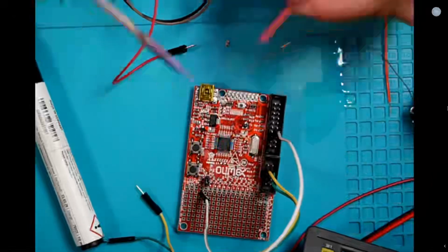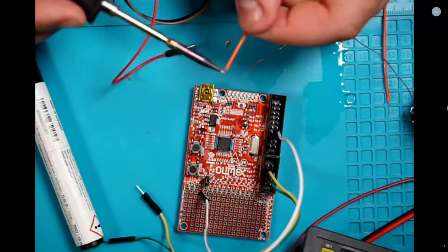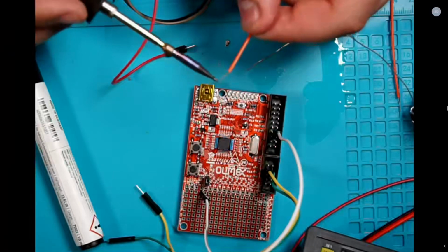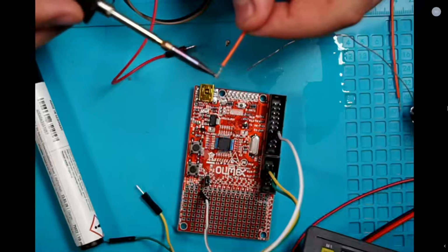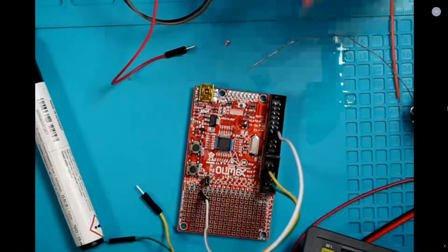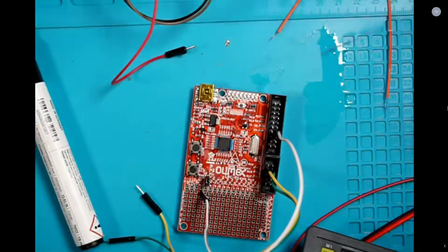And so if you solder enough, you might end up noticing that sometimes the solder doesn't latch onto, doesn't hold on to the end of the braided wire as well. So it's usually a good idea, if you have the chance, to cut off the tips, because usually there's no solder there. So that's what I'm also going to do.